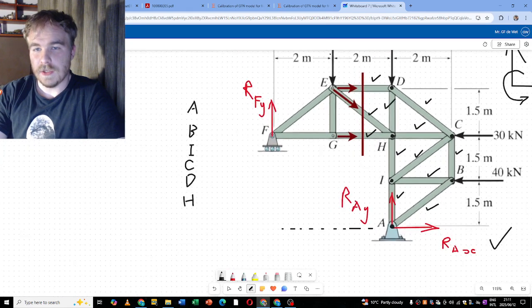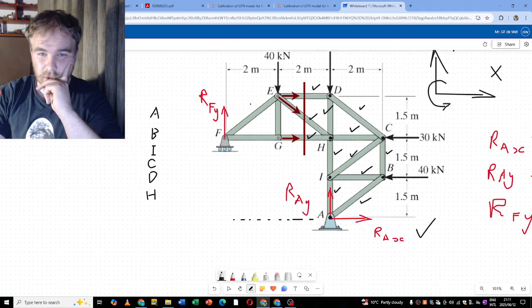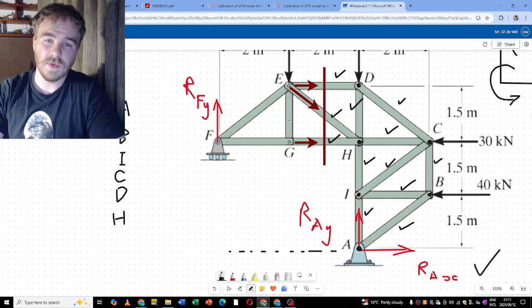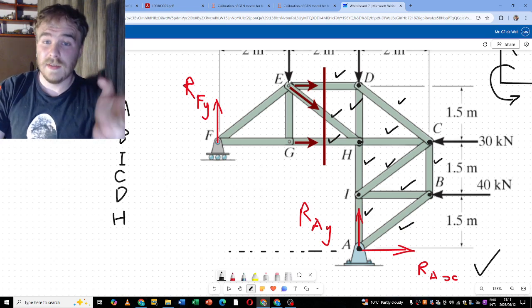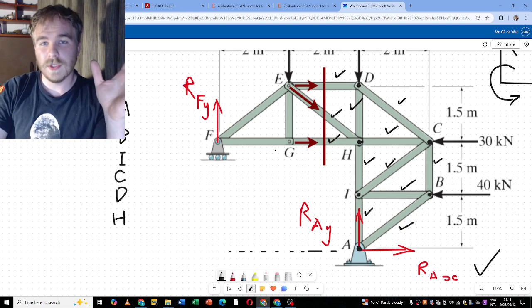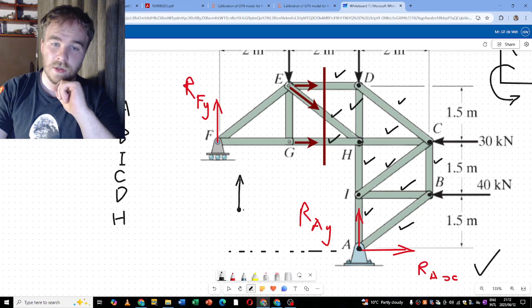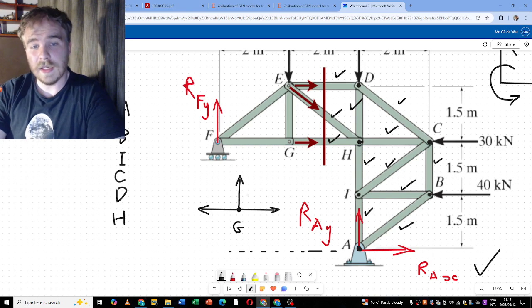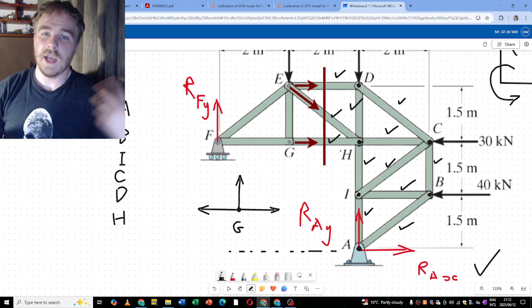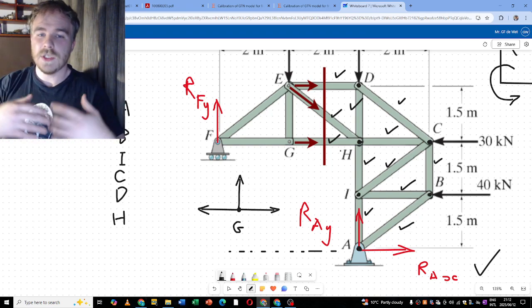You see something here is we actually do not need to calculate all 15 of these forces because we can argue about some of them. And that is that EG will be a 0-member force. The reason for that is when you look at the free body diagram, and we again assume that all of the forces are in tension, or that tension is positive and compression is negative. So we do our free body diagram assuming all tension forces, and all the forces need to be aligned with the members, because these are 2 force members. They cannot have forces to the side, otherwise they would want to spin.